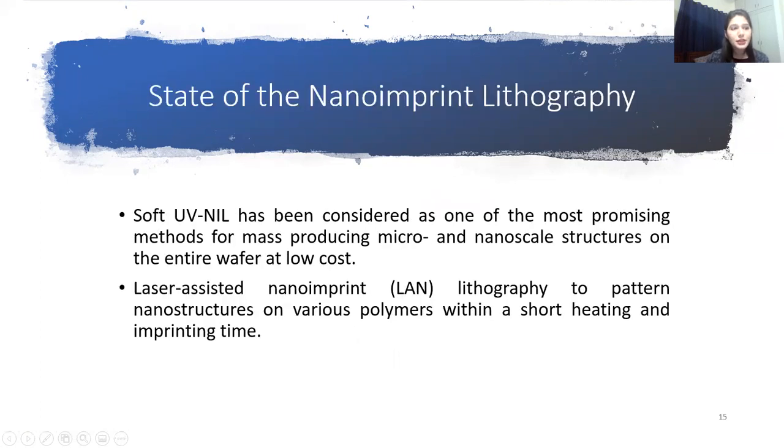Nanoimprint lithography has emerged as an attractive patterning technique and has developed considerably in terms of material, process technology, and equipment. In recent years, another technology has proven a wide range of capabilities, leading to its recommendation as a production suitable alternative lithographic method. Particularly, soft ultraviolet NIL is a very flexible and efficient technology capable of producing a large variety of structure, size, and shape, including complex shapes and 3D patterns, without compromising mass manufacturability.